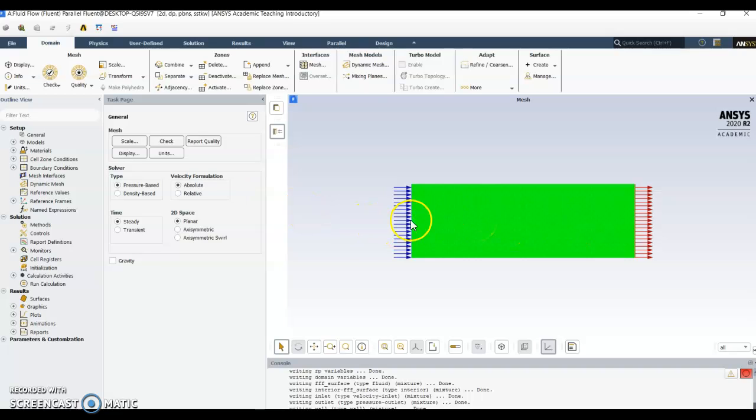If you're trying to simulate a jet engine, where obviously if you go above Mach 1, the speed of sound, the fluid will compress and density goes up, so you can have different densities in your model, so you need to use a density based solver. But yeah, if you go on Google pressure based solver ANSYS, you can get a page with answers written on it. It's like an ANSYS handbook that explains everything about pressure based and density based, all the methods behind it and stuff. Steady simulation, not transient. That would just take too much time, and I haven't got the space, I think, on the computer.